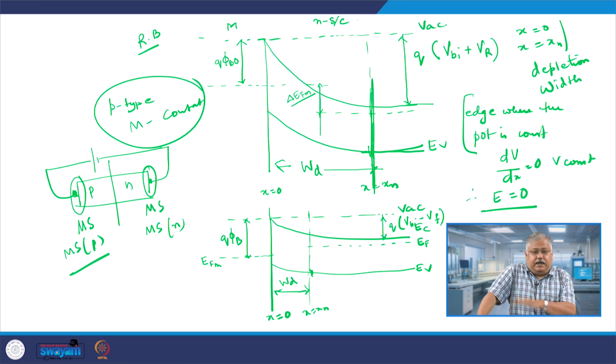If it is an n type semiconductor with negative bias, then the barrier height starts to reduce, and as you can see, the conduction band edge moves closer towards the vacuum, and you can easily therefore push the current through. Whereas in the first case, when you are applying a reverse bias, you are making the conduction band go well below the vacuum level, and as a result the effective barrier height on the semiconductor side increases drastically. Please understand, the barrier on the metal side does not change, it is still Q times phi b0, where phi b0 is the ideal metal side barrier.